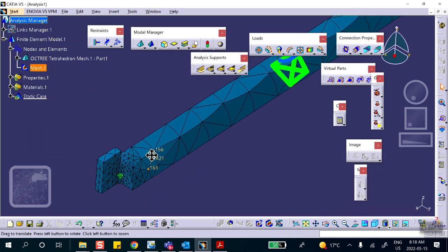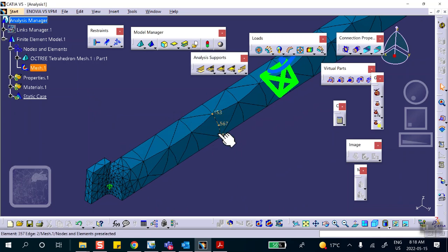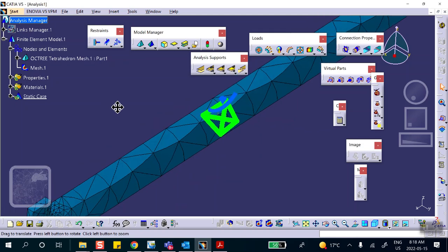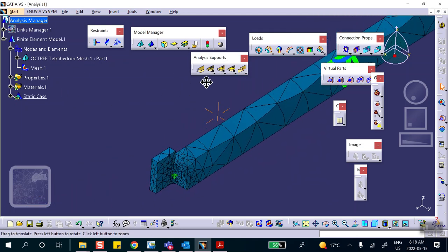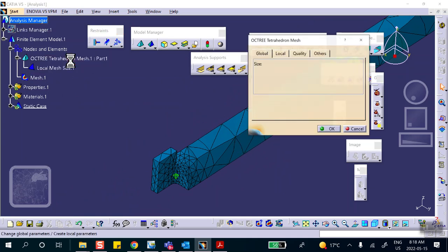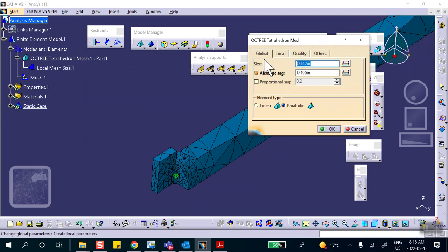It's right there. Okay. The very fact that these elements are big, it's a terrible mesh. And you see the faces are not even following the cylindrical border. So I'm going to make this thing smaller, just so that it looks a little bit nicer. Maybe 0.3.